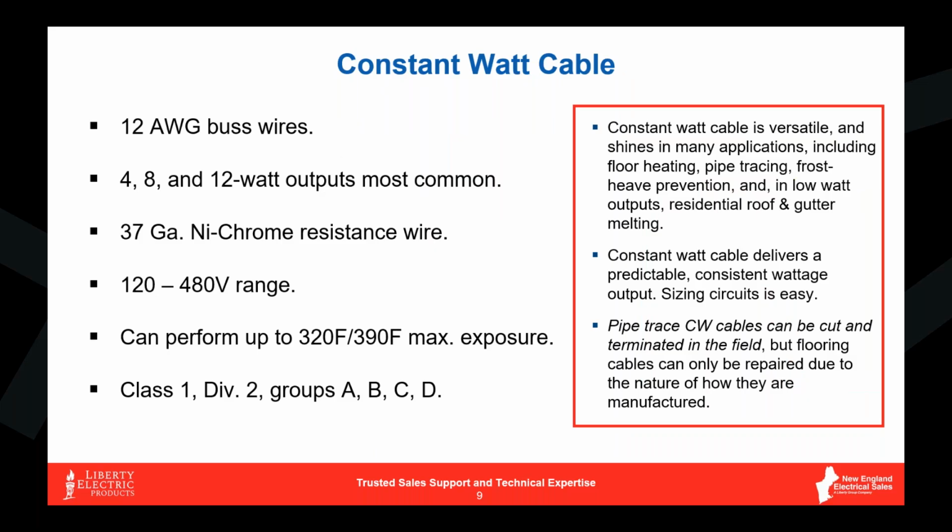You take 4, 8, or 12 watts a foot times however many feet and divide it by your voltage, and bang, there's your amps. The bus wires are generally a little bit thicker with the constant wattage cables versus the self-reg cables. And the nichrome resistance wire, which I've always found fascinating, is a 37 gauge wire that basically creates the heat inside of these products.